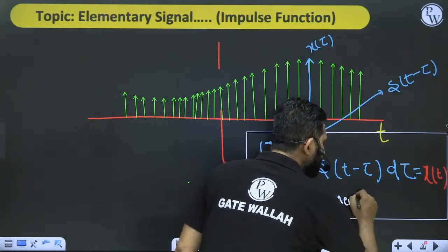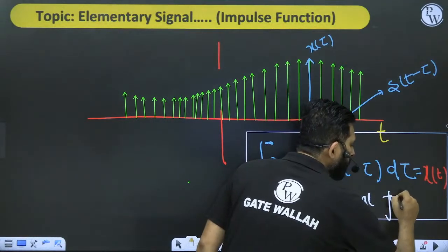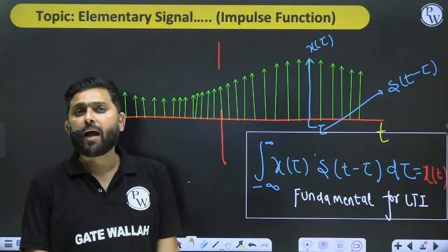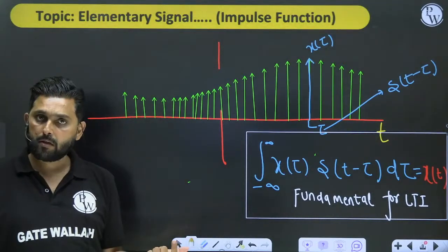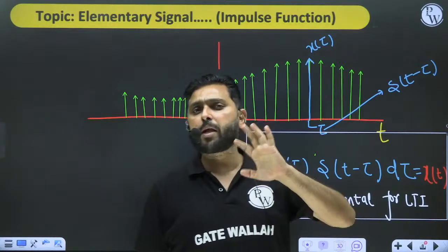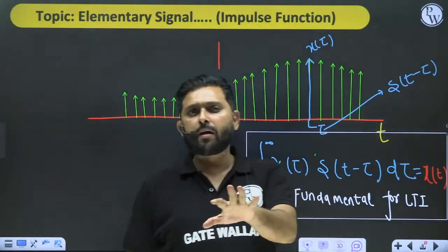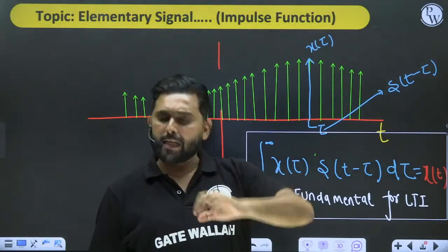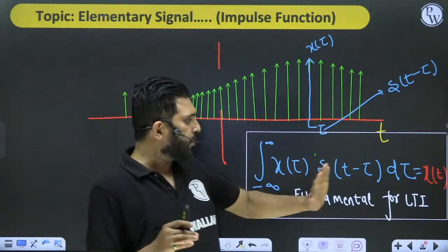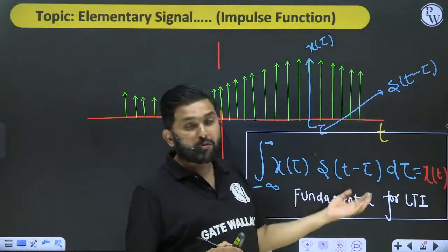Fundamental for LTI. So have you ever wondered why we always want the impulse response? See, in a control system, we always want an impulse response whose Laplace is the transfer function. But you never heard that I want a step response; you will get it from the impulse response itself. But what is fundamental? Fundamental is the impulse response of a system. Yes or no? Impulse response you must know.